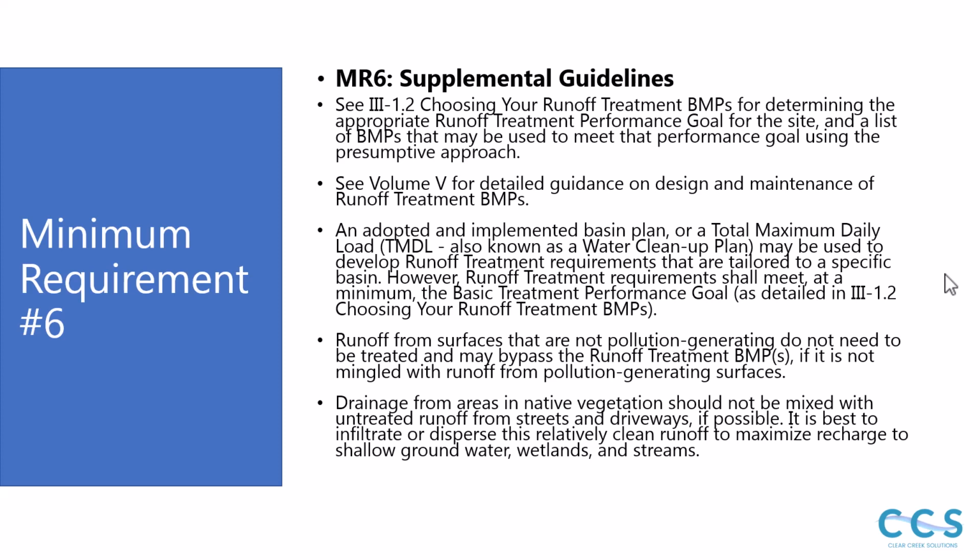However, runoff treatment requirements shall meet, at a minimum, the basic treatment performance goals as detailed in 3-12, choosing your runoff treatment BMPs. Runoff from surfaces that are not pollution generating do not need to be treated and may bypass the runoff treatment BMPs if it is not mingled with runoff from pollution generating surfaces.